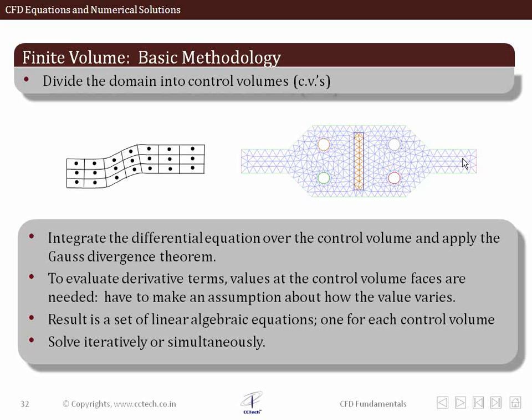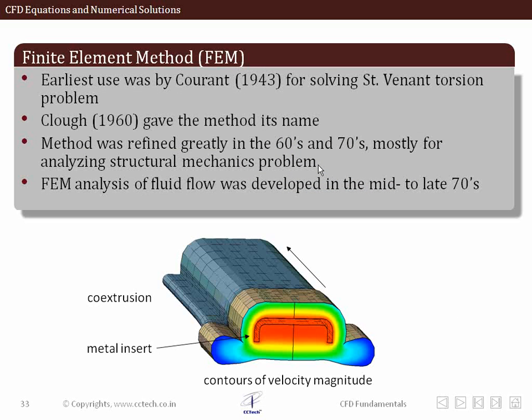The finite volume method can deal with both structured and unstructured mesh, as you can see. And again, the philosophy is quite similar: we'll try to discretize each and every equation and apply it at each mesh point. In this case, these are usually the cell centers or the volumes generated around the nodes. And we try to solve all the equations for a given variable in an iterative fashion, and we try to arrive at the solution.